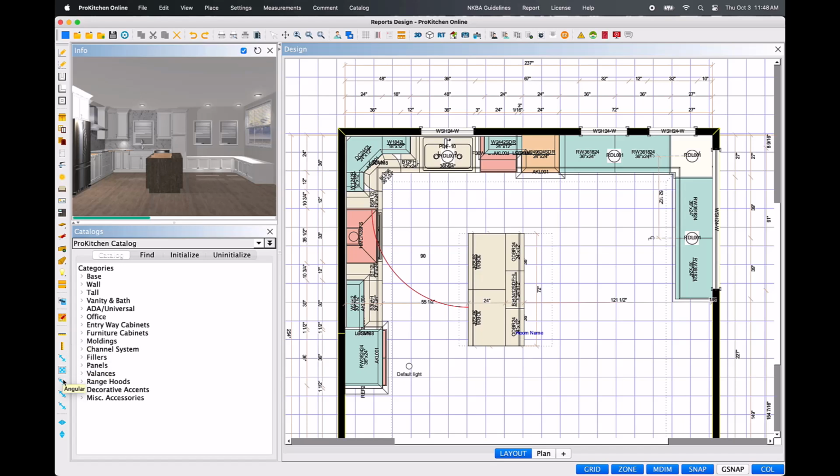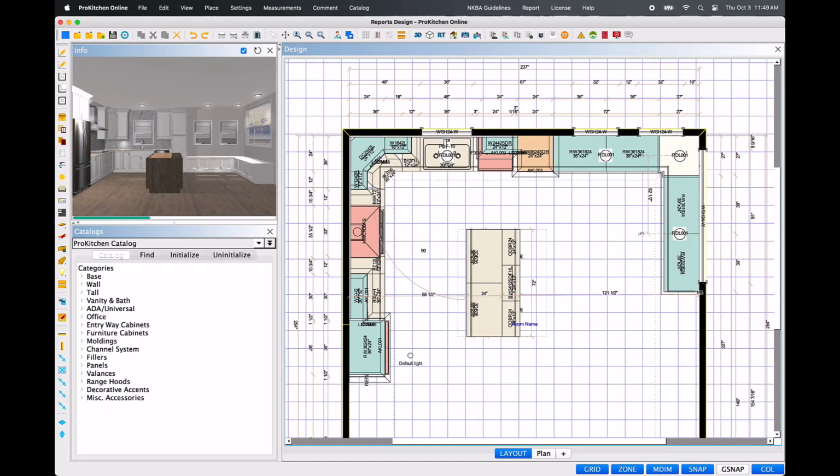Navigate to the left toolbar. Left-click the Point to Line icon to grab the tool. Bring the mouse into the plan view. Hover over the sink base until the purple circle appears. Left-click to start the dimension and drag the mouse to the left or right wall or item depending on where you need the measurement from. Once a purple line appears at the wall, left-click to create the dimension.